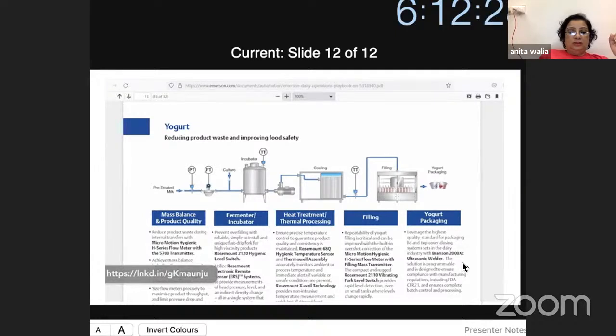And the steam pressure is basically monitored there with the help of a pressure sensor. The pressure sensor will send the data which helps in opening and closing of the control valve. The control valve opens and releases the pressure and regulates the steam. If the steam is too high, it will release the steam by opening the control valve. If it is too low, it will tighten the control valve.